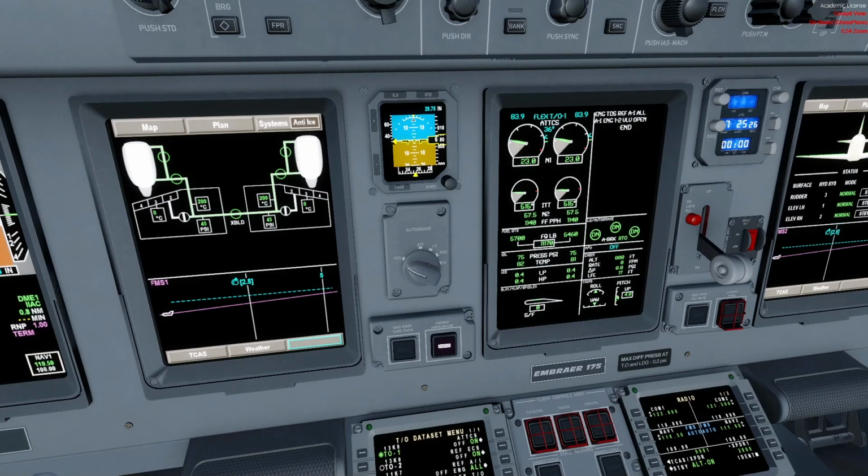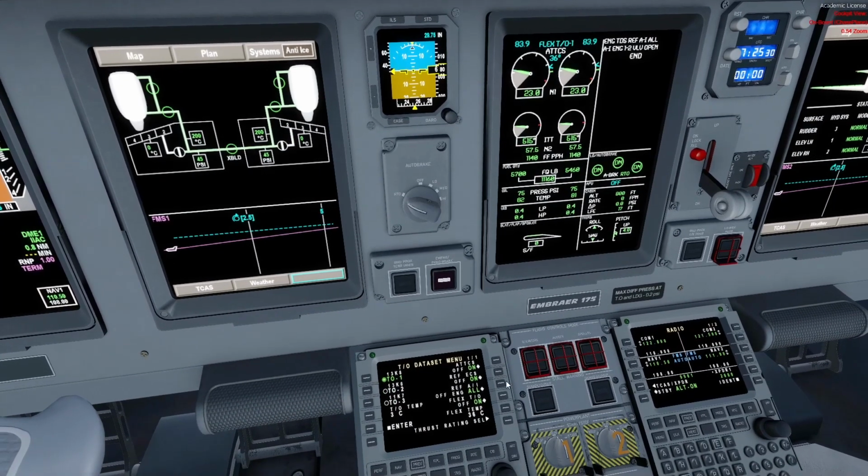So that's before takeoff. Now, after landing, let's turn off the anti-ice again. Yeah, so now you see the engine anti-ice is closed. We don't see the message anymore. The wing anti-ice is obviously closed. So let's say we've landed. So this is the before takeoff, and we said in flight the ice detectors mandate what's going to happen. Now after landing, it's neither nor, right?